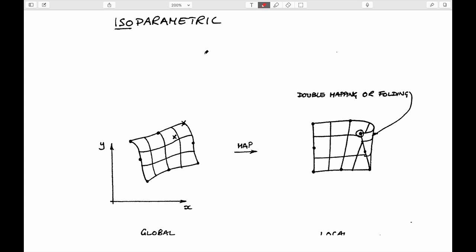The real meaning of isoparametric refers to the fact that iso being one, meaning one-to-one, one and one only if you like, is that if this was your geometry, that is your real geometry of the element that you'd like to represent by figuring out what the K-matrix is, the conductance matrix is, then when you map it to this form where you're going to do the calculation, the mapping should give you that every single point on here would be a unique point on this mapped form.